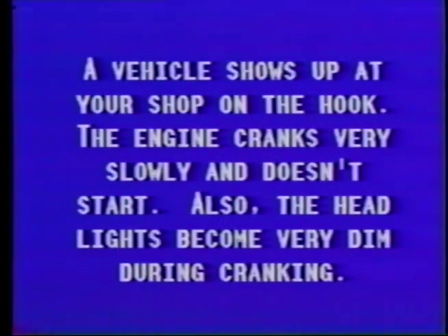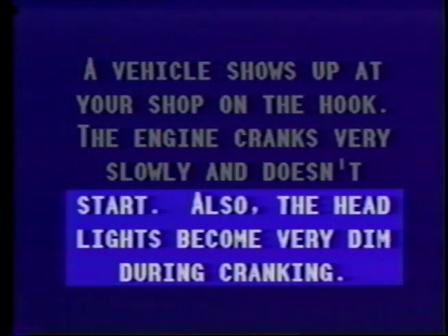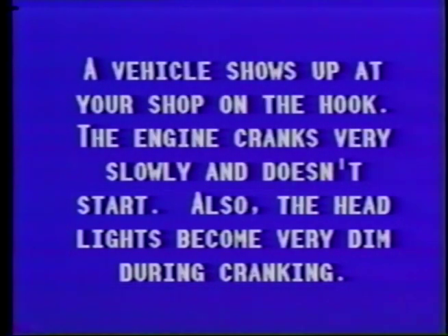A hint in the question indicates whether there is a low resistance problem, such as a short, or a high resistance problem, such as a dirty connection in the starter circuit. The statement about headlights dimming during cranking indicates a large amperage draw. So we're looking for a cause of very high amperage draw in the starting circuit.